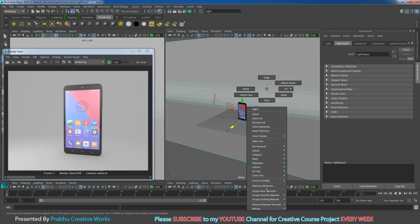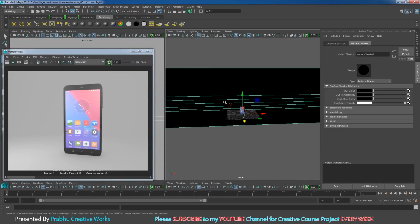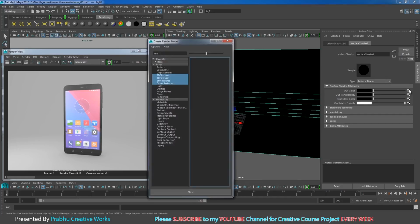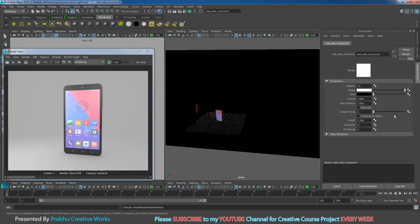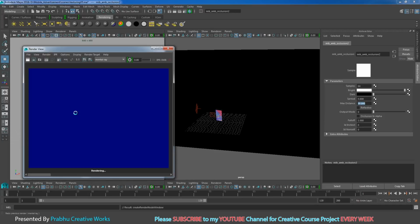Right click and choose assign new material. Here you need to choose surface shader. In out color, I will click on my out color, and here you need to give mental ray and choose MIB ambient occlusion, MIB ambient occlusion for my BG. Choose 64 samples and for maximum distance give at least 30. I will keep this image for comparison and click render.